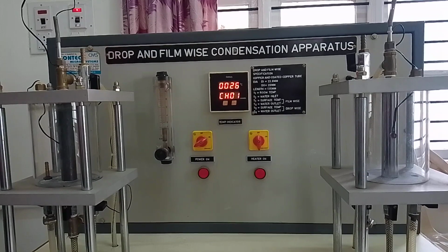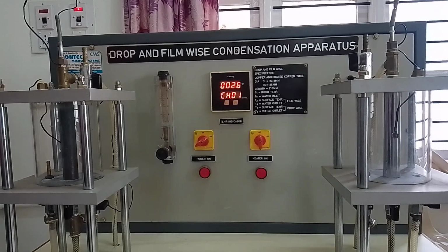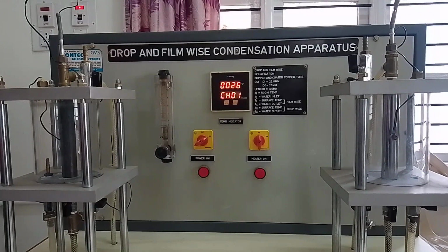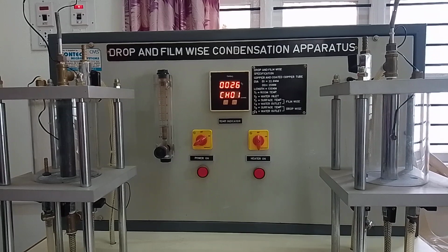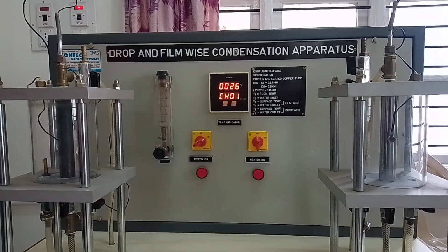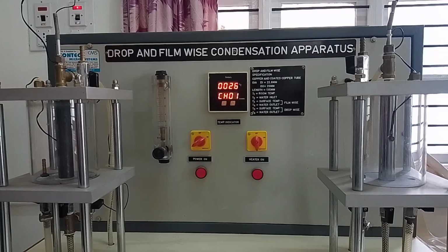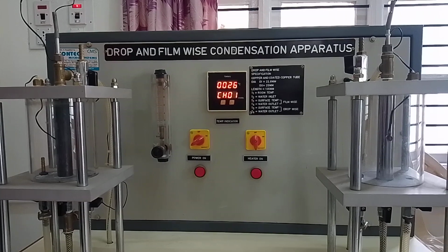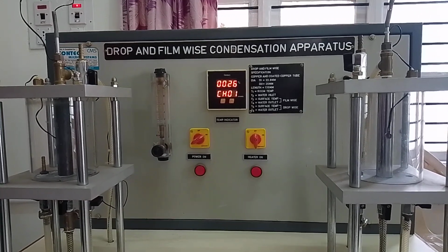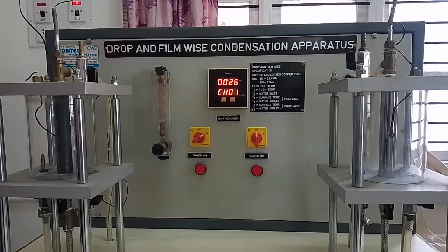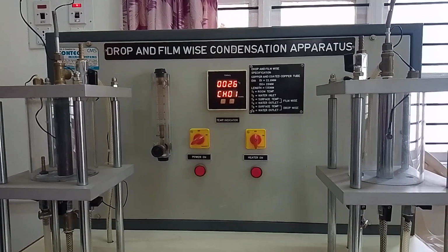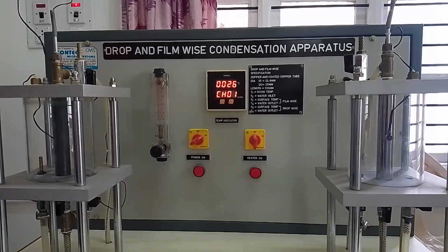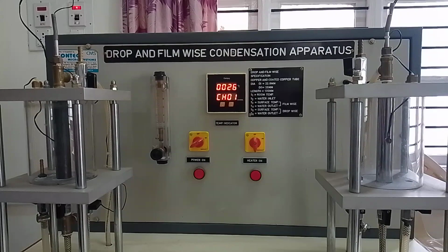In filmwise condensation, the surface is covered by a liquid film of increasing thickness, and this film acts as a resistance to heat transfer from the vapor to the solid. Therefore, the heat transfer rate is less in filmwise condensation. However, in dropwise condensation, the vapor condenses in the form of drops which slide down due to gravity, exposing the surface to the vapor. Hence, there is no resistance like film formation to transfer the heat from the vapor to the solid. Therefore, the heat rate is high compared to filmwise. However, it is very difficult to achieve dropwise condensation in practical applications.